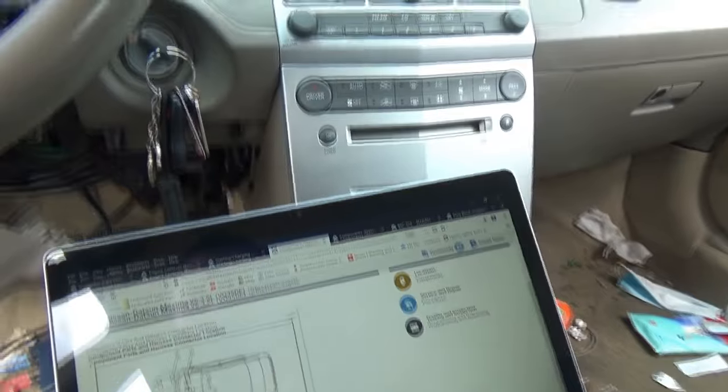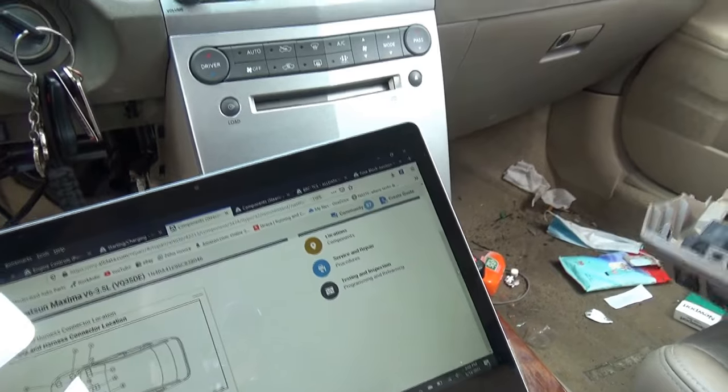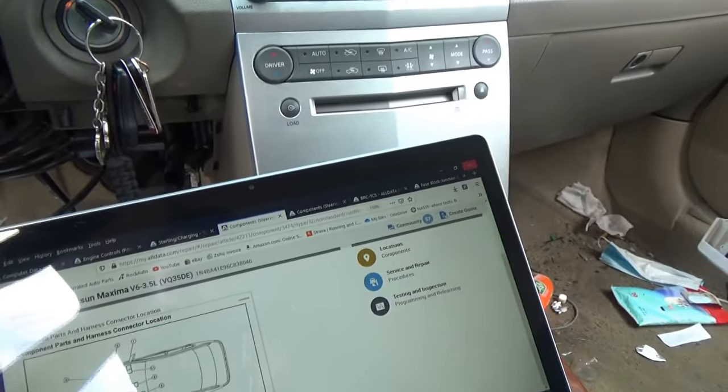We're mostly done with the diagnosis, but we still want to get this car to start. So we need to see the power distribution diagram for those two fuses and see if we can eliminate the module that's pulling this network down the ground. Crazy stuff. I can't believe it was the last module that I had to check. Well, apparently this car does not have vehicle dynamics control, it just has traction control. So I was a little confused here.